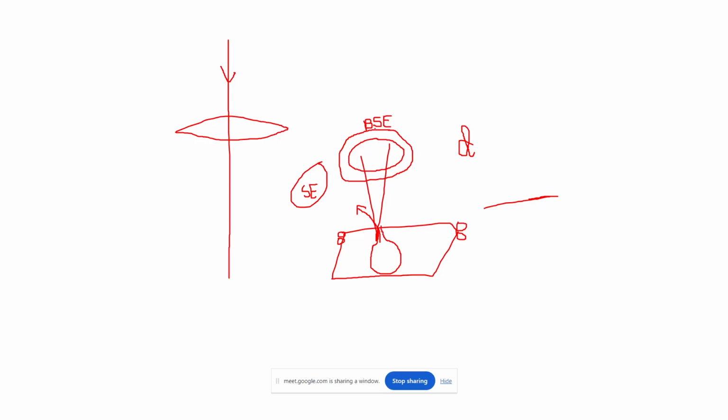So the BSE electrons will be collected by this detector, and the secondary electrons will be collected by the other detector. There are also characteristic X-rays, Auger electrons, and Bremsstrahlung radiation. These are all emitted every time, but depending upon the detector you use, you get information based on that detector.